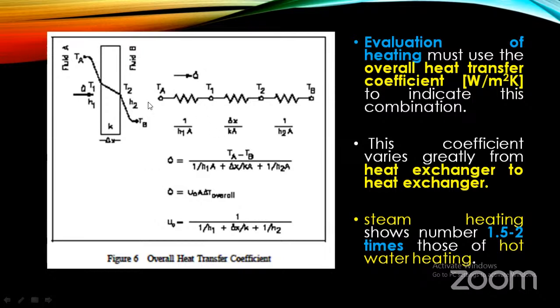On both the sides you have convection, and in between you have conduction. So that is what is designated by this thermal network. So the temperature TA is one node to be found out. Another one is the temperature T1, that is the fluid temperature, the temperature at this point. And T2 is the wall temperature at the other side.